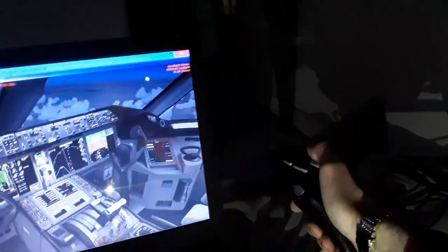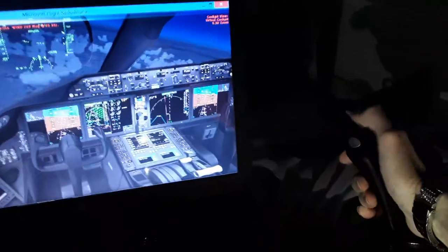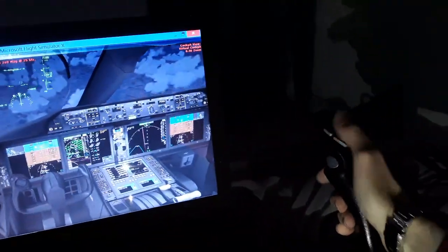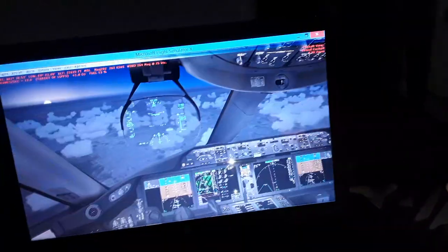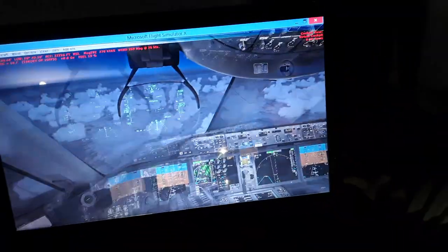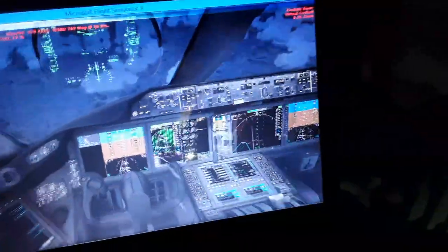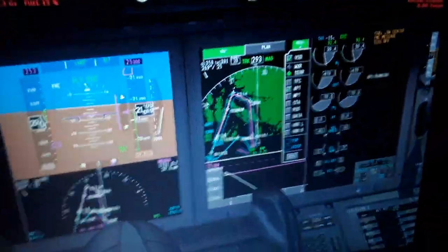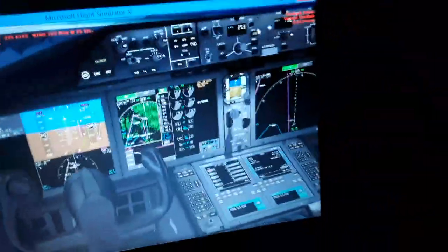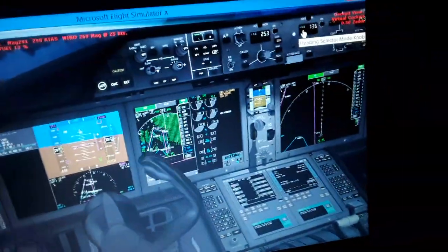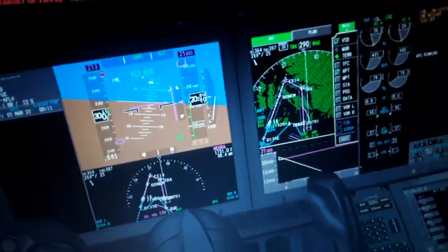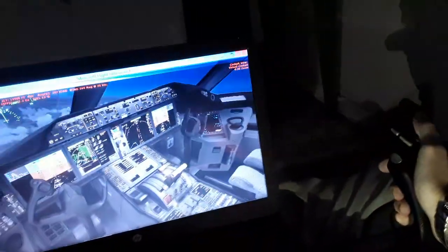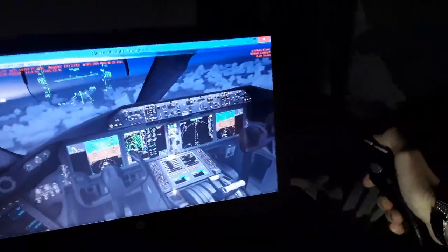Need to hold down the elevator and pitch trim the aircraft tail a little bit down. Keep descending. So we need to descend over here from this altitude back to the airport elevation and traverse through some waypoints here that you can see. We need to make a small turn out to the left to align with the flight plan here. Use a little bit more thrust.